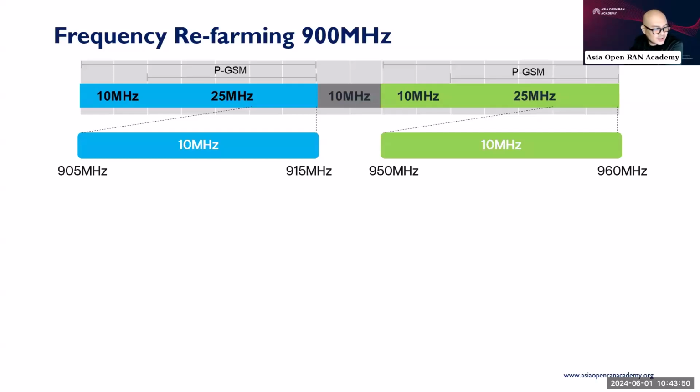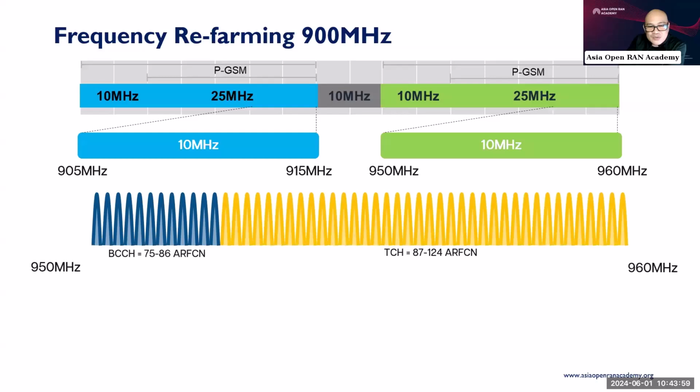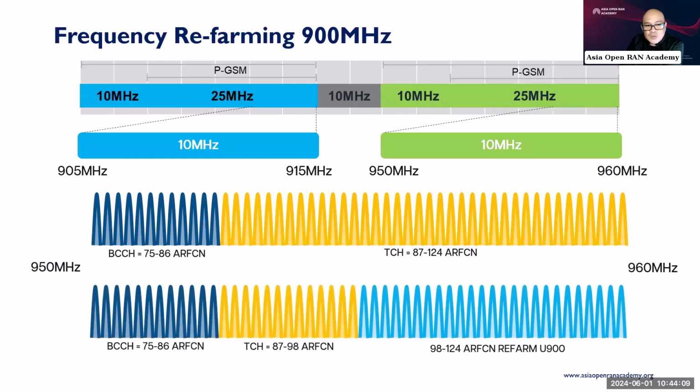So what you are planning to do, so I still have 5 minutes now. So what you are trying to do, you will divide it into different subcarrier or different frequency channels in the 2G, 200 kilohertz each. So you'll have this kind of scenario. And then you will use this into a broadcast channel and a traffic channel. And then after that, if you want to use this frequency in UMTS, you can use it for UMTS.